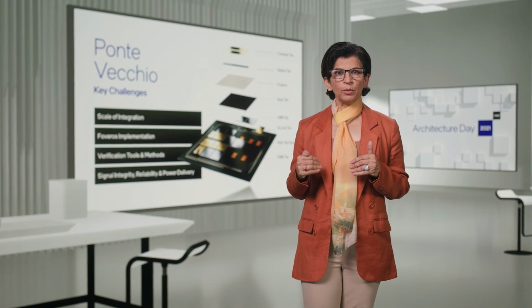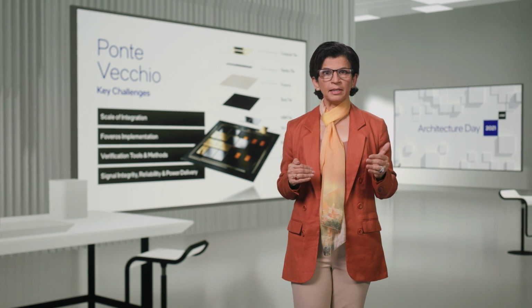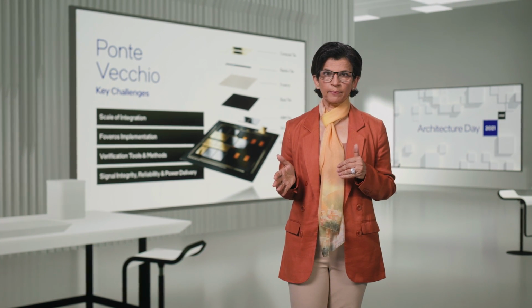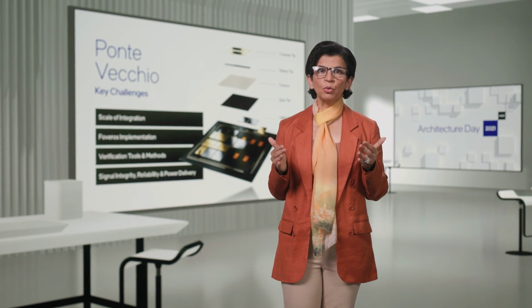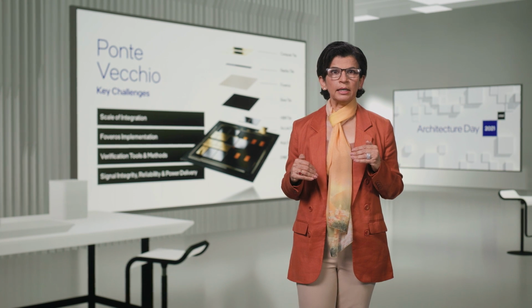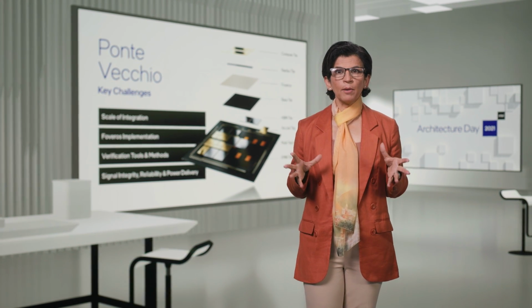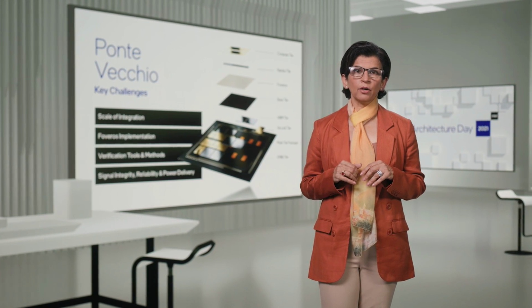Since we pioneered this 3D implementation, we had to innovate continuously on die-to-die implementation and verification methodology. We developed many tools, methods, and scripts in real time and performed validation at multiple levels of hierarchy with new BFMs and test benches to keep the tiles independent and keep hierarchies clean and crisp.